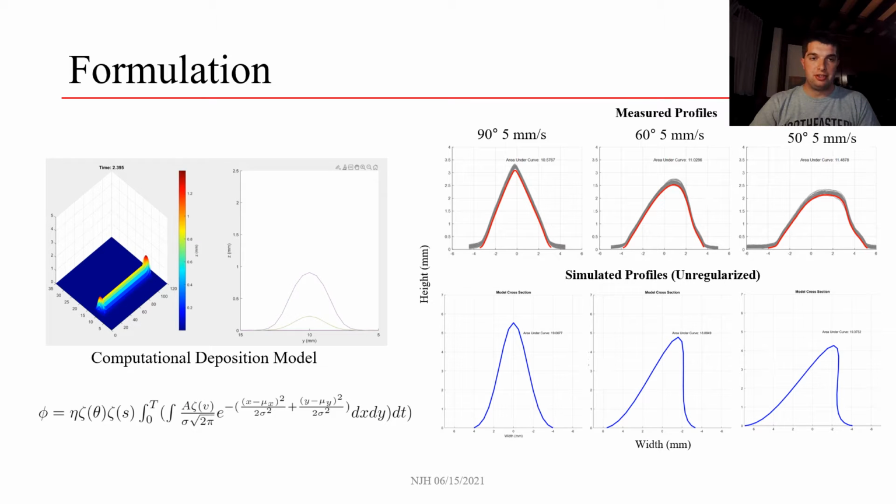At the core of our research is a MATLAB computational deposition model, which uses a bivariate Gaussian distribution to model the surface growth of a cold spray deposition. With this model, we're able to make predictions, then go out into the wild with our cold spray system, deposit simple rasters, and then compare the two. And by tweaking hyperparameters, we're able to yield a computational model which enables us to accurately plan and predict the forms that will be deposited by more complex sprays.